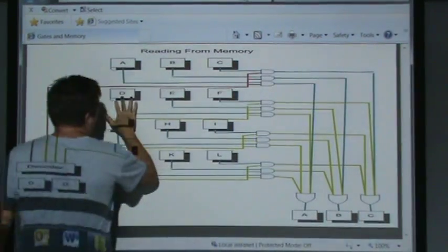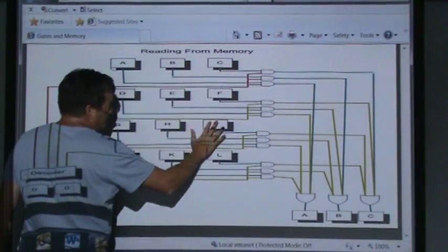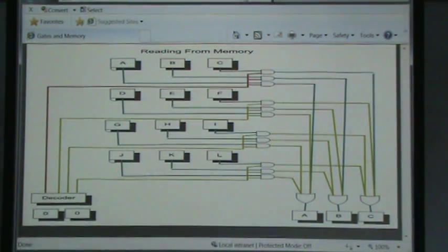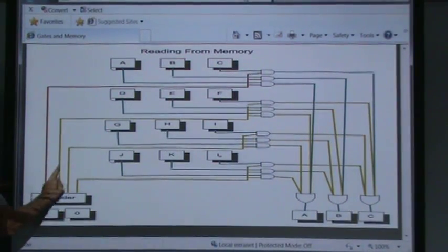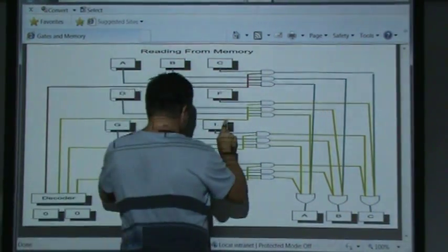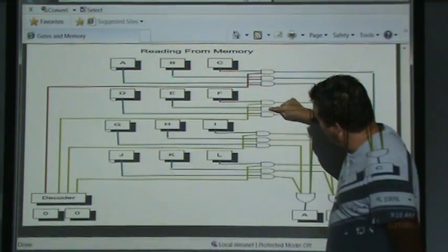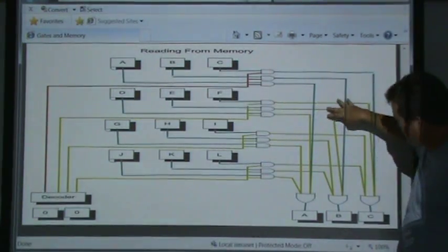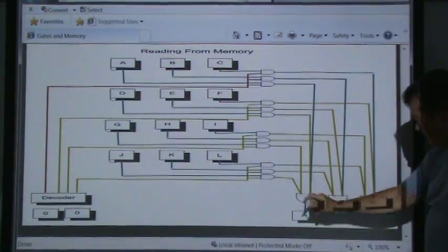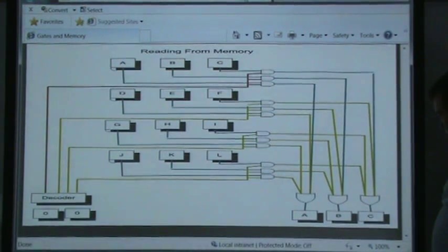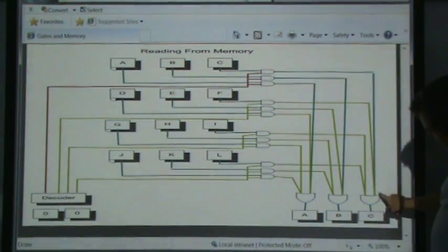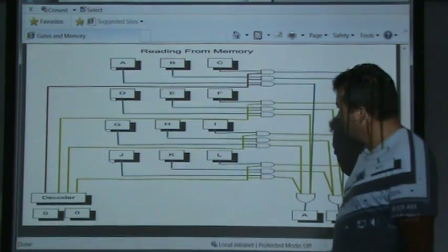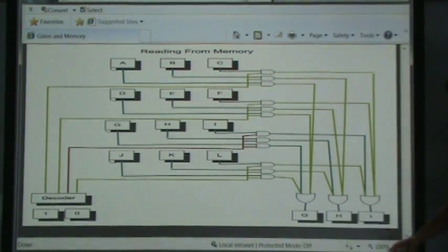As for the memory cells of the second, third, and fourth bytes, their values will not show up in the answer, because this electricity being off causes these AND gates to all produce zeros regardless of what the values in memory are, and a bunch of zeros go down into these OR gates. These are OR gates, they're just not drawn like OR gates, because I spun them using Visio. The same is true for here and here.